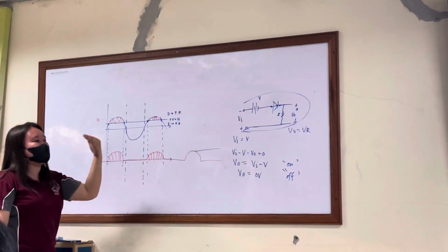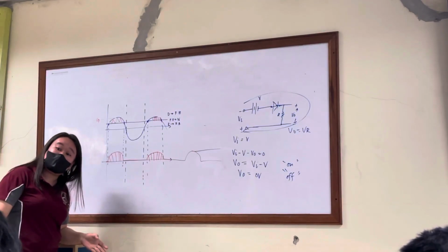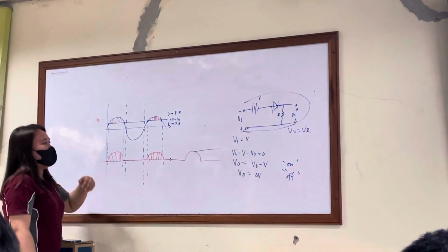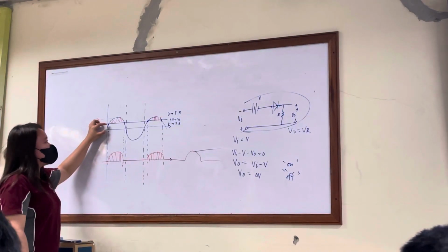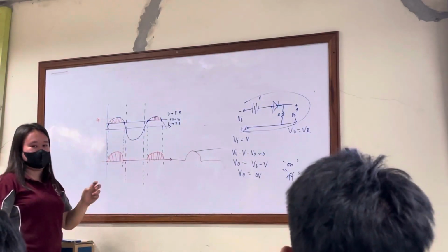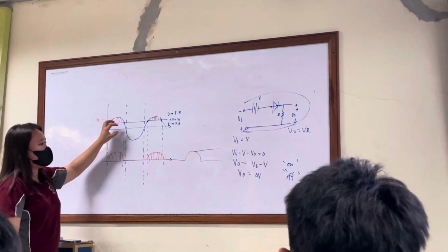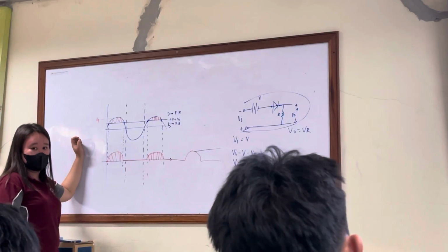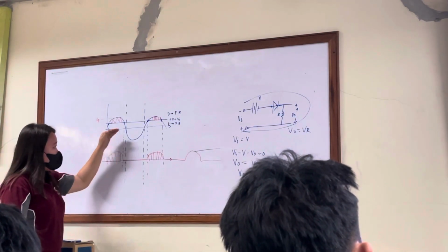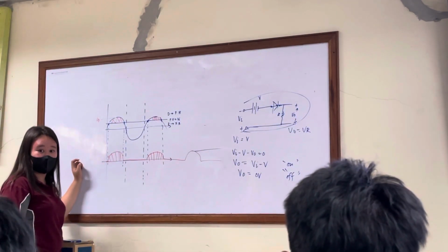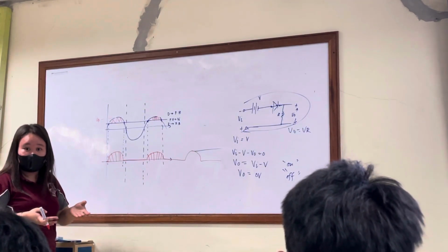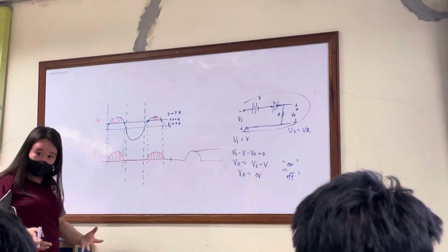So it is not just a half-wave rectifier. True, it is half-wave, but we are clipping a portion from our positive half. Upper half, clipped. Lower half, all clipped. So you see the clipping: taking away a portion of our signal.